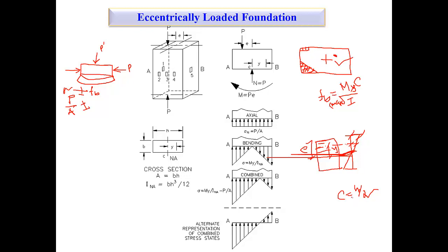Okay. So C equals half of H, right? We know this total is H. So whenever we consider C, it will be half of H. So in both directions it is the same. We know compression and tension are equal from the very basic design. You have studied this in RCC also, in the assumptions of the design, while you develop the equation for beam design and others, right? Yes, sir.